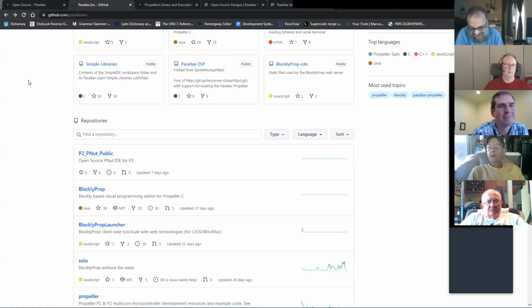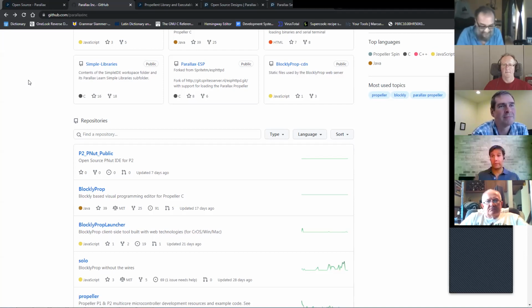Yeah. So my two cents is the debug screens are excellent and we should keep them. The only thing I'm using the PST for with my students is for inputting data from a keyboard to the Propeller 2. We've talked about this before, that because of Windows and the way it works with the serial ports, it's not easy to do that. But I was thinking maybe we could have some kind of special command to send through the debug, like the wait key in the old keyboard objects for the P1. So somehow wait for a key for an indefinite amount of time, or wait for a specified number of milliseconds and then give up and keep continuing the loop.